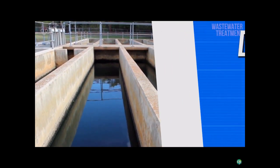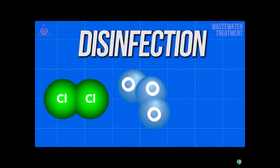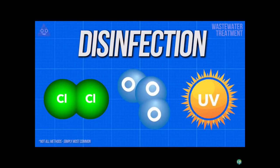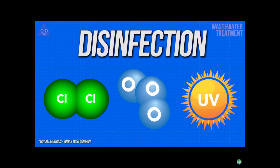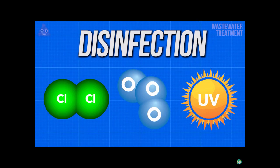Disinfection is the final step of the process and is usually accomplished in one of three ways, either through chlorine, ozone, or ultraviolet disinfection. Each process has its benefits and drawbacks, with each being used commonly throughout the wastewater treatment process across the world.